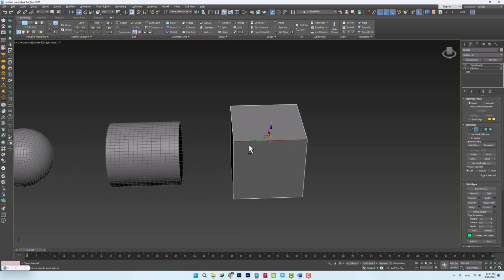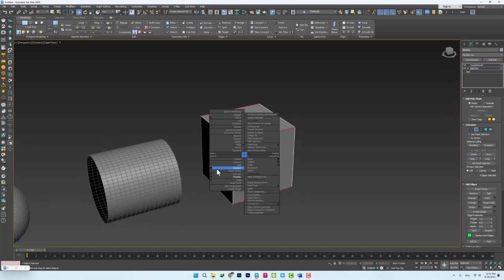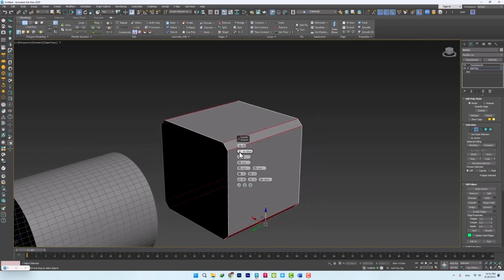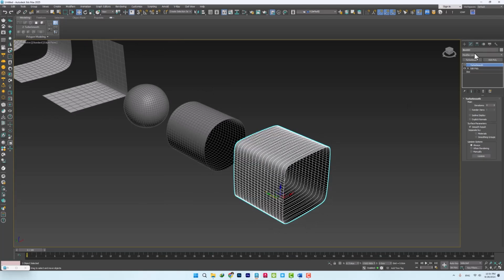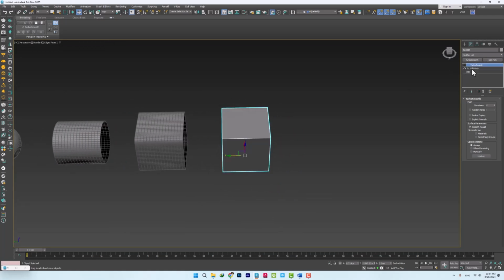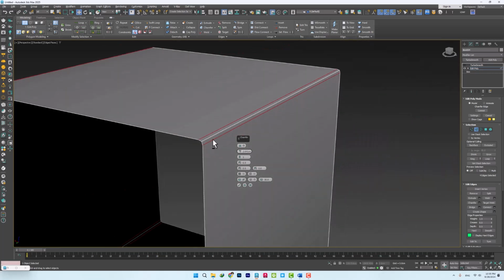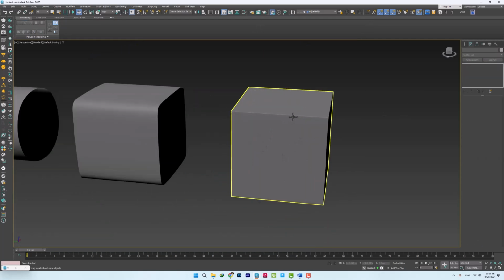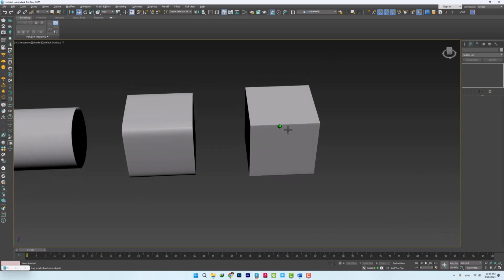Now, if we take another copy of the shape and select its edges with the help of Ring and finally chamfer it, we will see that, with the addition of Turbo Smooth, the working edges become sharper and keep their shape. Next, we copy it again and create the chamfer with a smaller number to reduce the distance between the lines. In this case, Turbo Smooth creates the edges with the highest level of sharpness. If we assign the material to it, we can see the difference in them more clearly with the help of specular.